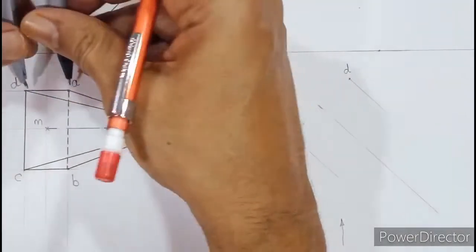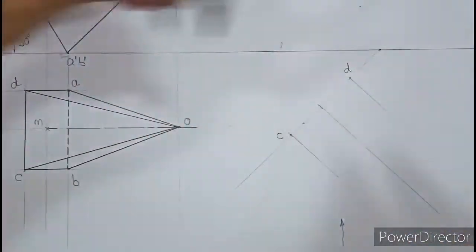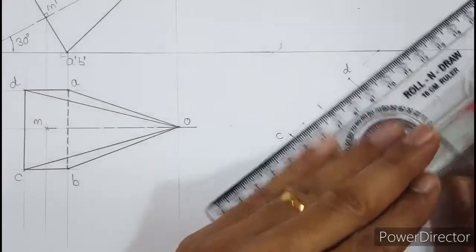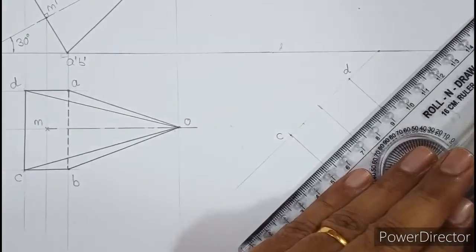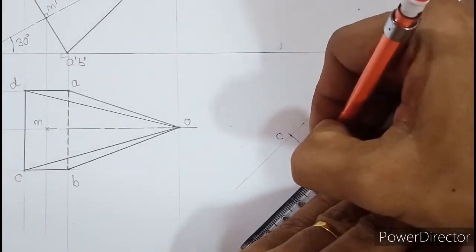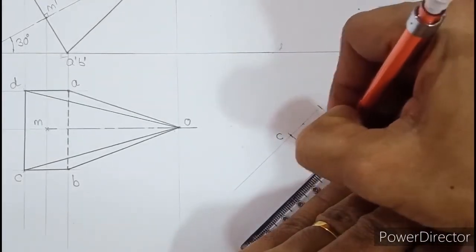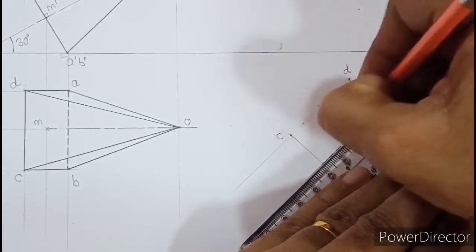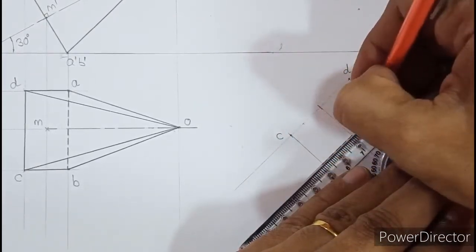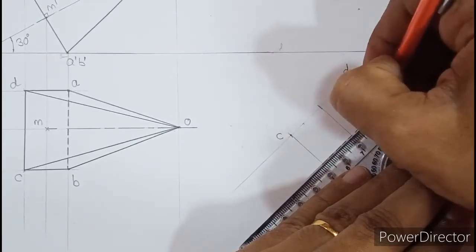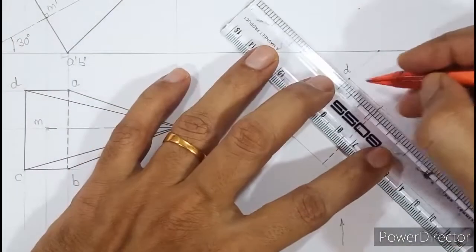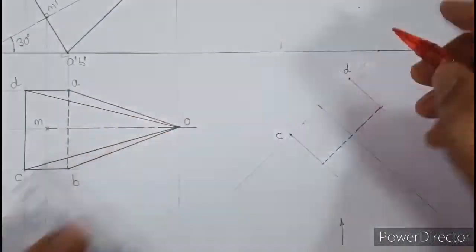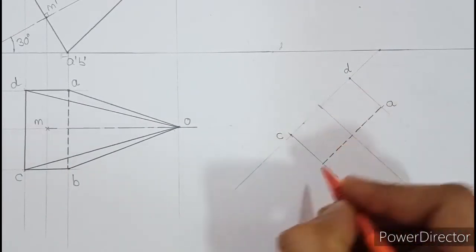Then, because the size and shape will remain the same, take D to A in the compass, and from D cut an arc here. Okay, and just copy paste the same diagram. So align the roller scale with D to C, roll it down, and draw the hidden line dark. If the original diagram is dark, you need to produce a replica of it, just producing the same diagram. So say I have drawn that line here, and darken this portion here. So this point is A, this point is B.